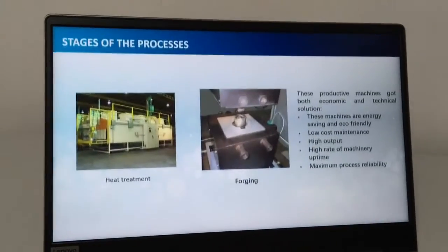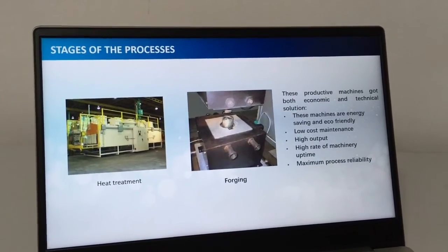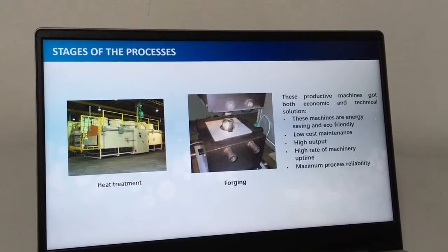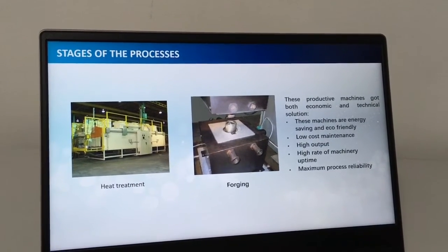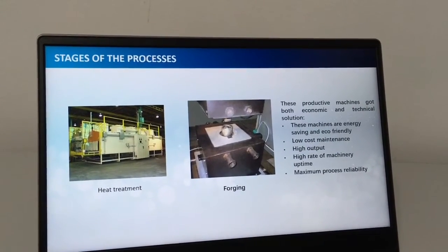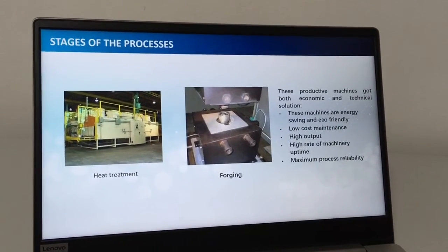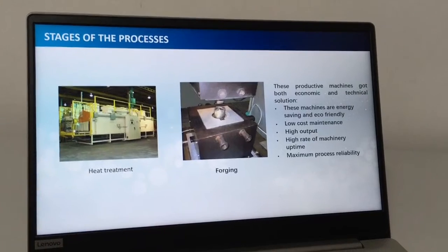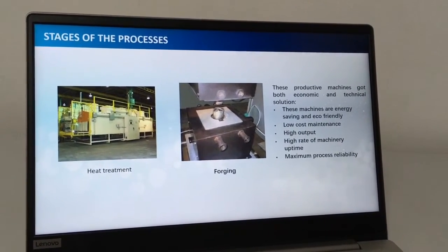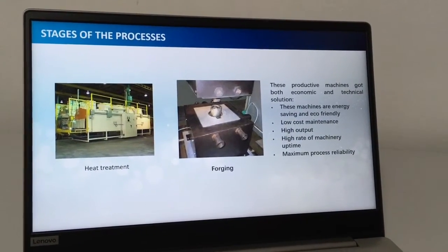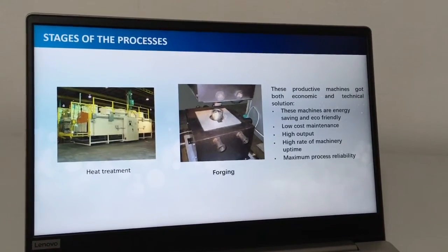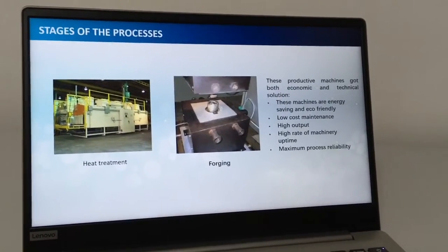For this articulated rod, we will discuss the forging process. Due to the common structure of the hinge rod, the die required for forging is simple and can be produced very fast. For the machining process, because the forging is rough, the size is not accurate.